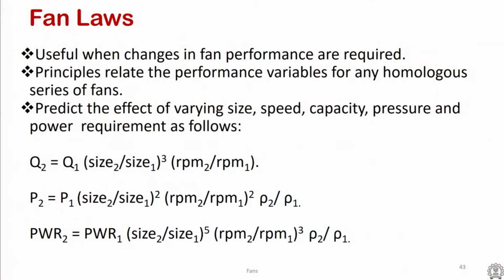just describe them. If you are just interested in scaling up from a given fan without changing any other thing, if it is an 80 millimeter fan and you want to go to a 120 millimeter fan, or you want to understand the effect of a 120 millimeter fan, then using these fan laws, one can easily obtain what could be the flow rate, power, pressure, back pressure and so on. So the fan laws are quite useful in such situations.